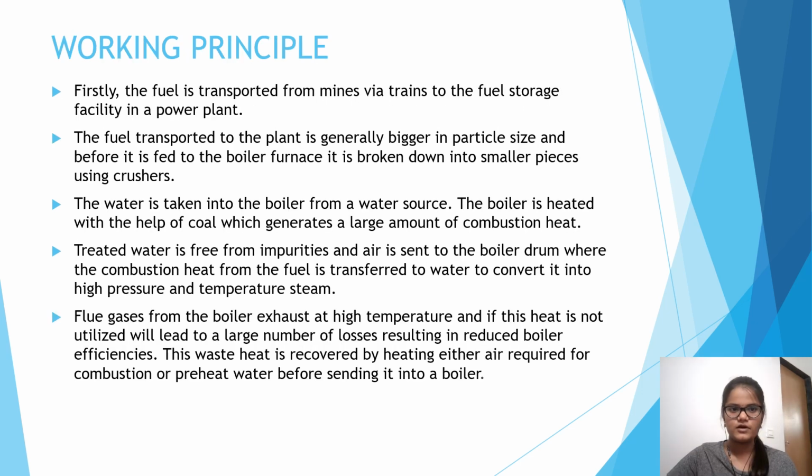Let us discuss the working principle of a thermal power plant. Firstly, the fuel is transported from mines via trains to the fuel storage facility in a power plant. The fuel transported to the plant is generally bigger in particle size, and before it is fed to the boiler furnace, it is broken down into smaller pieces using crushers.